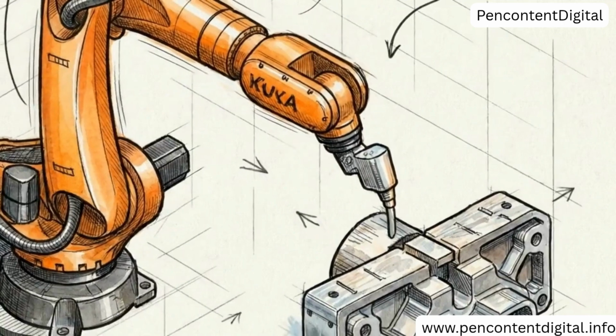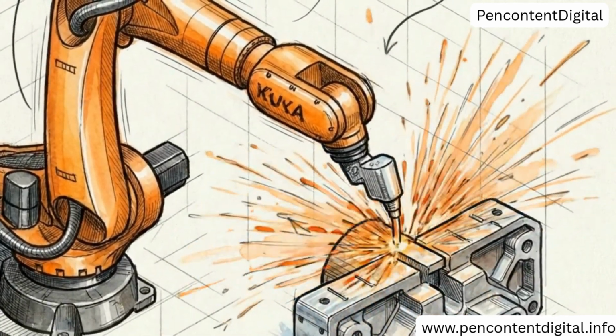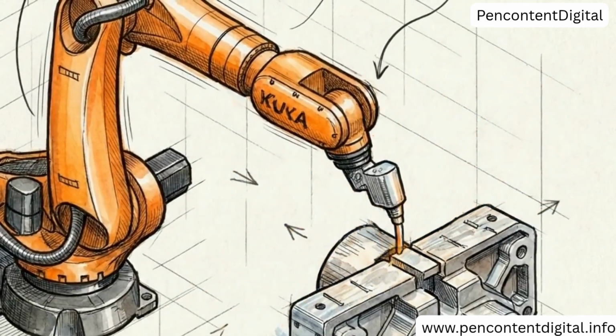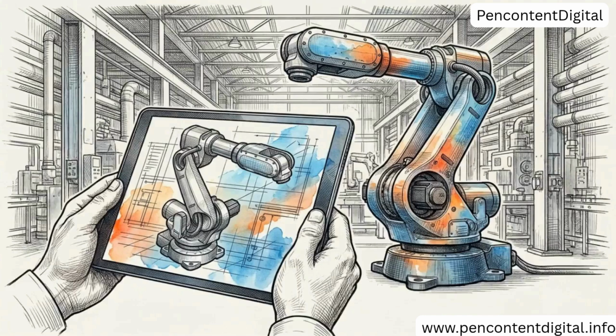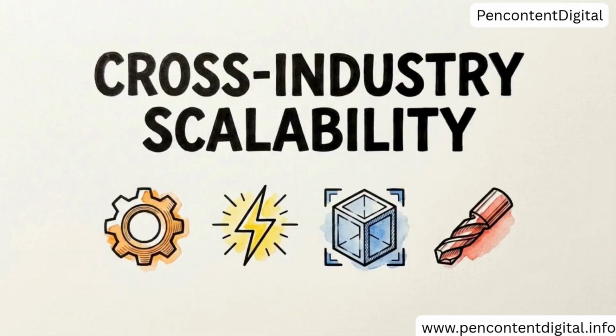Built upon precise kinematics and tested against strict spatial rules, the physical robot executes the program exactly as it was validated in the simulation. The post-processor bridges the gap, translating the theoretical perfection of the digital twin into the practical reality of the factory floor. This pipeline, transitioning from a static CAD file to an optimized, natively coded robotic program, can be executed with zero production downtime. This offline programming architecture is highly versatile, deploying across different industrial sectors.